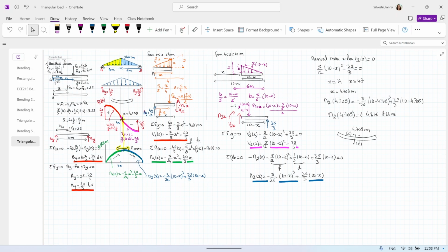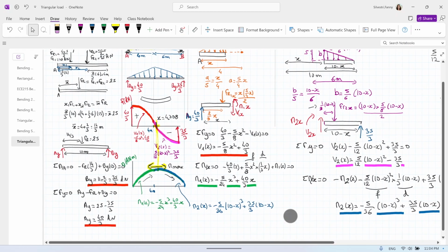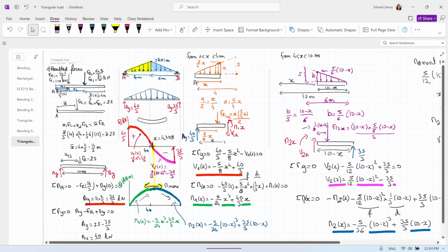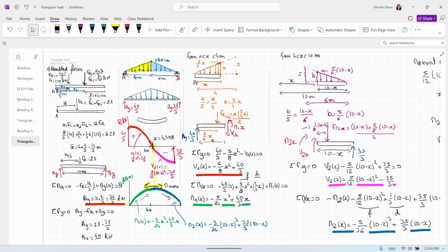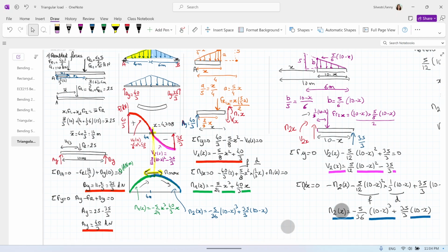And yeah, go one step at a time. Find the reaction forces. Sometimes to find the reaction forces, you need to find the resultant forces first from the distributed load, and after that, cut your beam into segments where the distributed load changes. So here we make a segment from 0 to 4, and after that 4 to 10. Be careful where x is. Be careful what your maximum triangular load is, because we cut it. It's not anymore 5 kilonewton per meter. It's smaller than that. So similar triangle rule, and take the time to write your equations. Don't forget your distance when you do the moment equation.